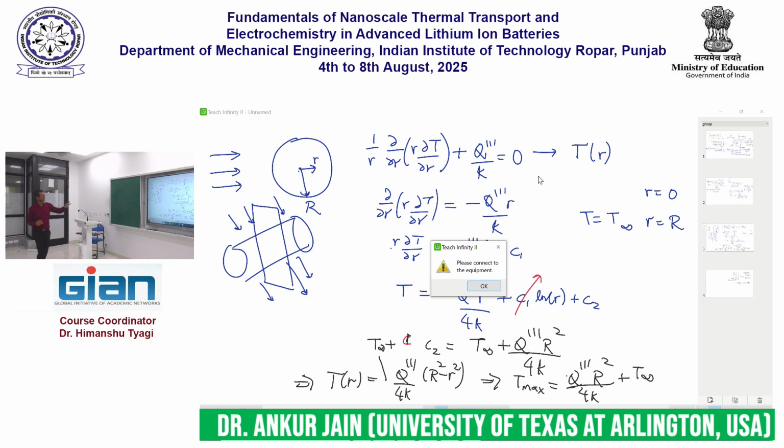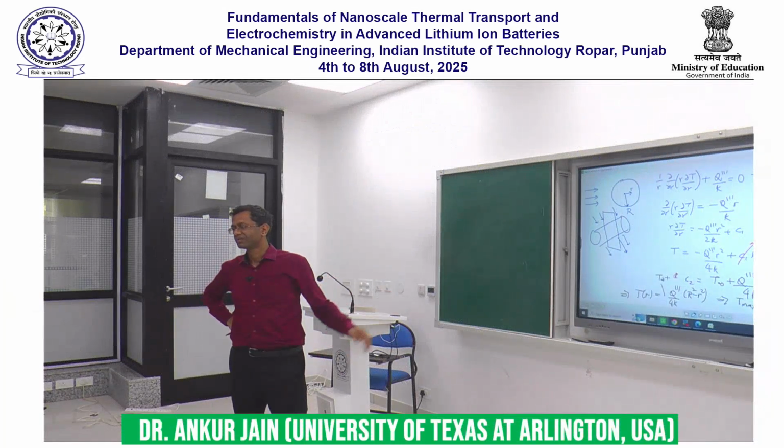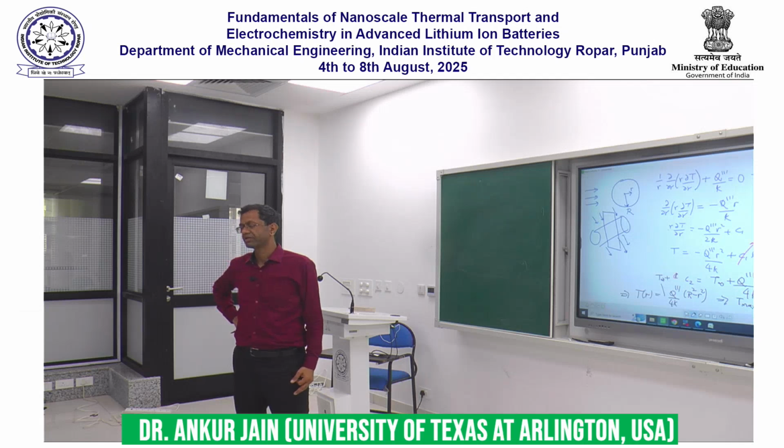So this analysis is fairly simple. What Tesla does is something more complicated. They actually have channels around the cell for a coolant, liquid cooling. And the analysis of liquid cooling is more complicated; they might be using heat exchangers. So that analysis is slightly more complicated than what we have done here. It's a generalized one. So prismatic will have a lesser amount of heat dissipation compared to the cylindrical. Correct.